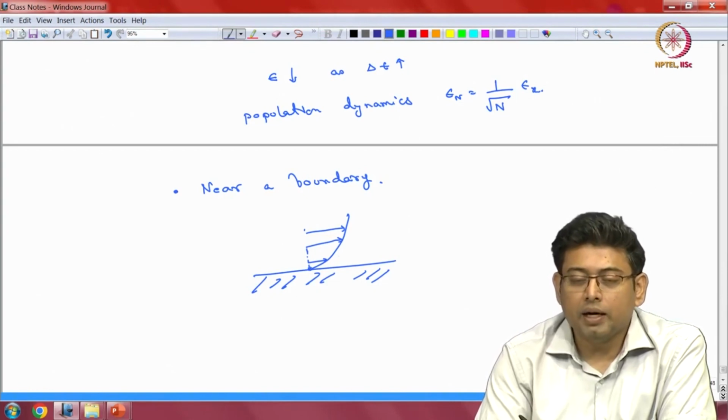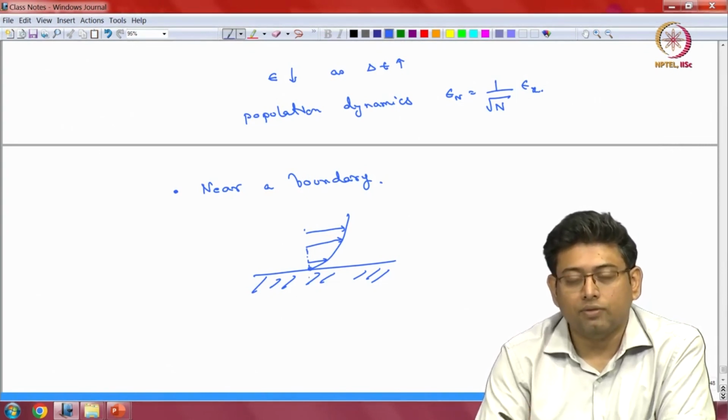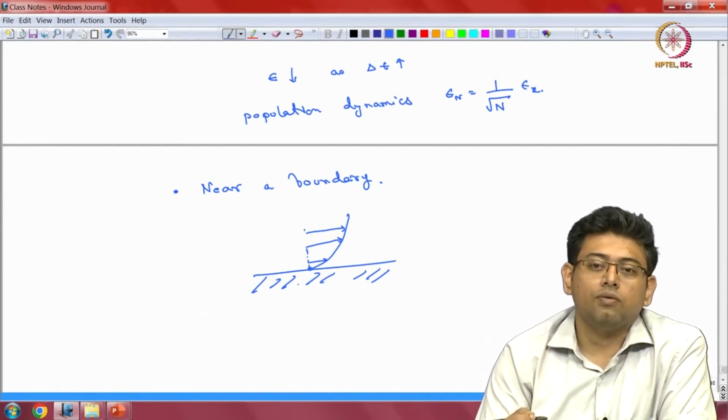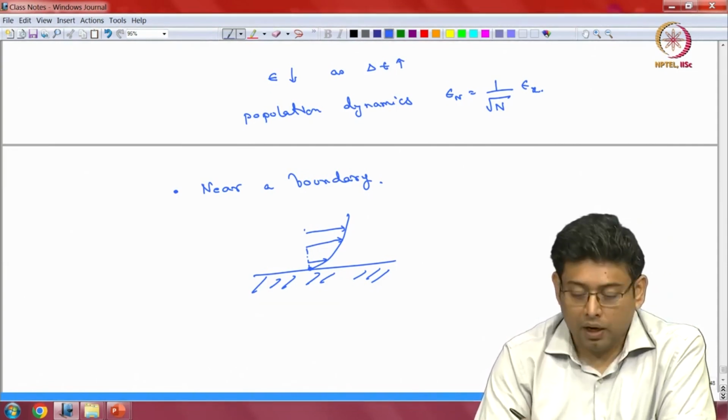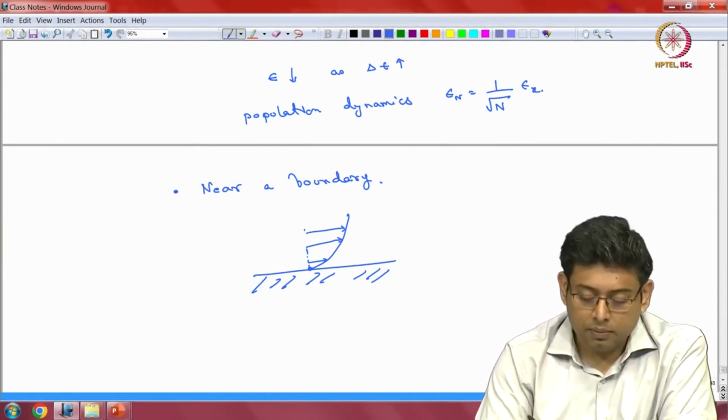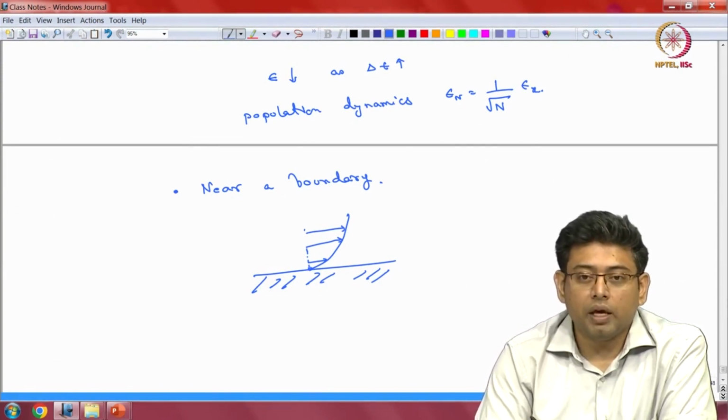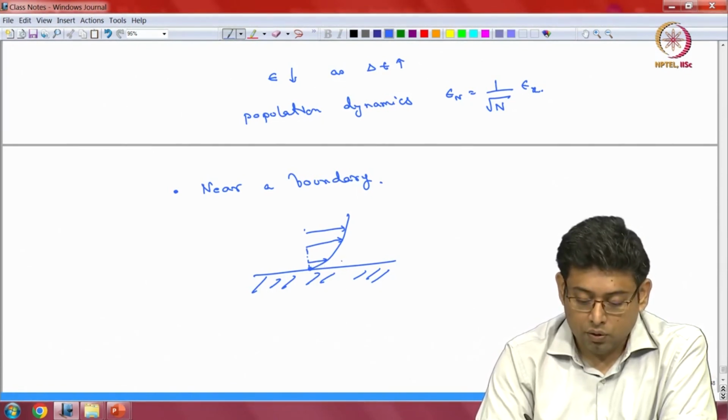So the relative velocity between the fluid particle right at the boundary and the wall is zero. This condition can be violated under certain cases. You can have slip, for example, in nanochannels, or if the flow is very sparse, and there are some other cases, but the no slip condition is a very common case in continuum flows, and it's almost always used.